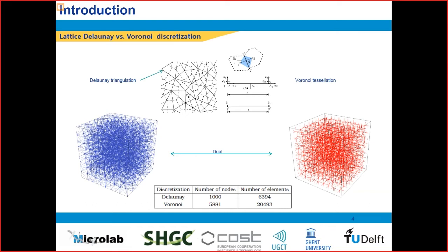In the case of fracture modeling, our discrete elements are always, or at least so far in the literature we have seen that they are always, the Delaunay triangle edges. And the two nodes belonging to the elements possess certain degrees of freedom, such as the displacements in the local XYZ directions and the rotations around these axes. You can see the Delaunay elements in the upper image in the slide with continuous black lines.